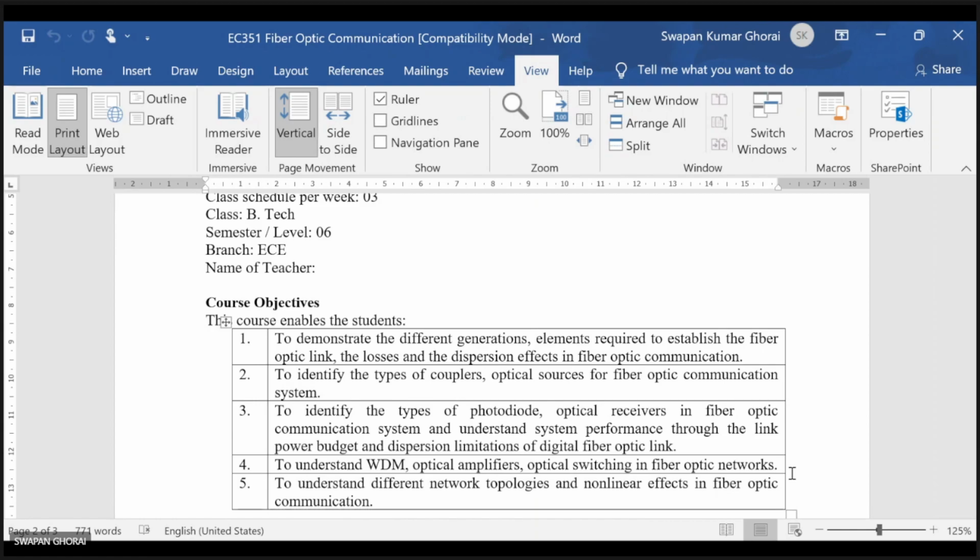Because of those effects, if you use WDM systems, the channels will not be uniformly amplified, and some power penalty will be required for different channels. Because of the uneven power distribution, we'll see the Raman effect, the Brillouin effect, and four-wave mixing.